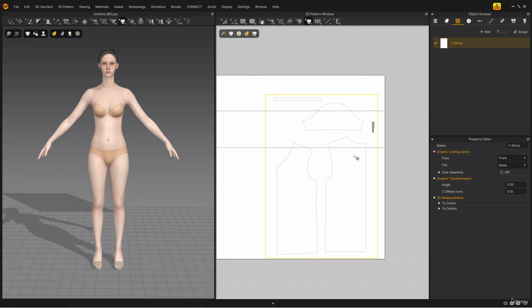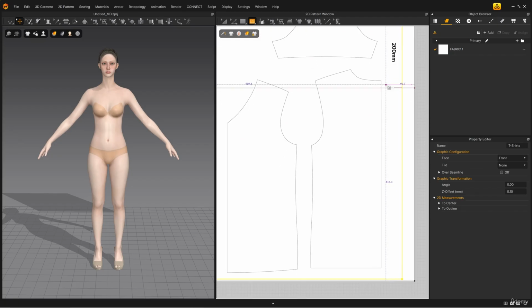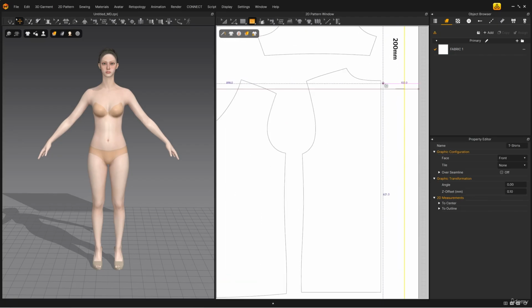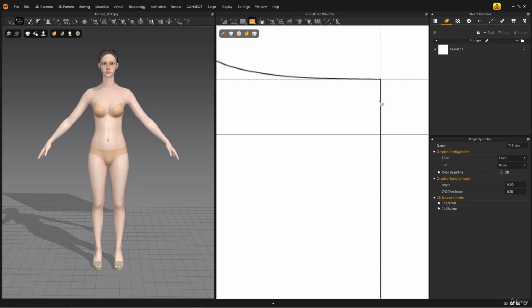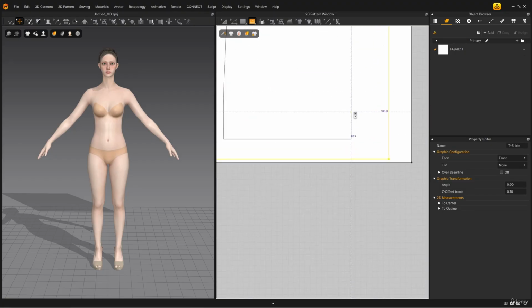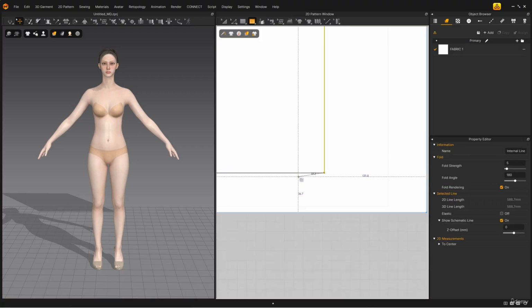From the toolbar, select the Internal Polygon Line tool. Now you'll click along the edges of the pattern in the image to trace its outline. Click normally to create straight line segments between points. If you need to trace a curve, hold down the Control key while clicking. This will create curved lines that follow the contour of the pattern.